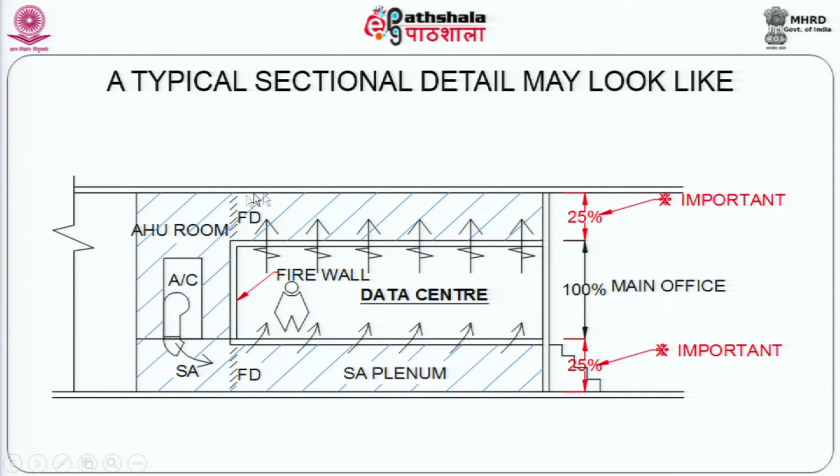From an architectural designer's point of view, it is interesting to note that for such a large volume, the usable volume is only this much. If you really calculate by cubic meter, you will find that perhaps the data center occupies maybe 1/2 or even less of the total, because this is handling CFM at about 700 CFM per ton. Corresponding to that, you need a big void here.